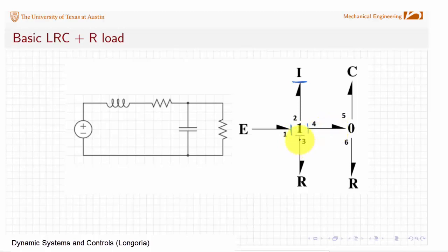Now we've got a flow here, flow coming into the R, that's okay. And now we can apply integral causality on the C. Now that's imposed the effort here, which means that R has to have effort in, which is the effort across that capacitor, which should all make physical sense. Okay, again, two independent energy storage elements, lambda, Q, two states, lambda and Q.